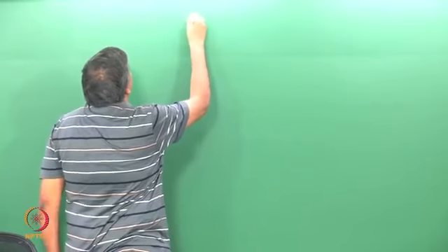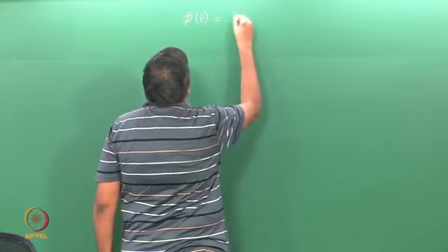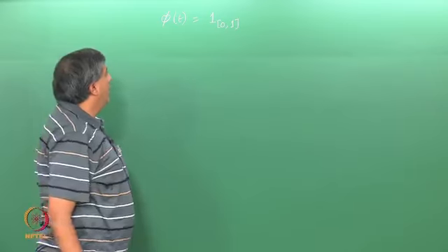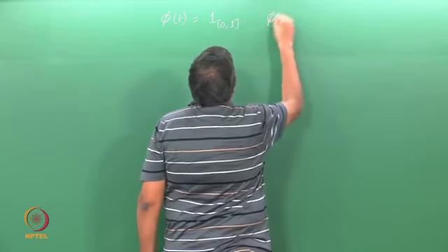So, assume that this scaling function or the wavelet that we have plotted is available here at the same resolution as the signal, and we want to generate phi of t by 2 or even phi of t by 2 minus 1. Then let us first understand by hand how to generate these values. If I am given phi of t, which here we know is the box function in the interval 0 to 1, which means it is understood to be 0 outside this interval, then I would like to construct phi of t by 2.